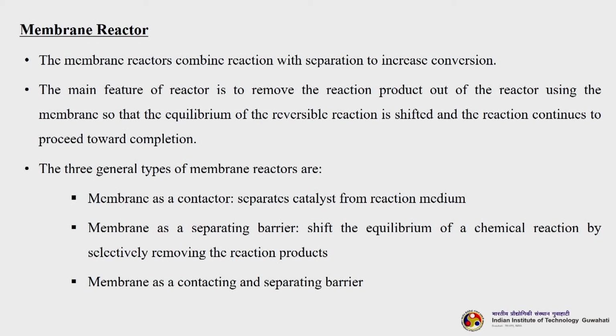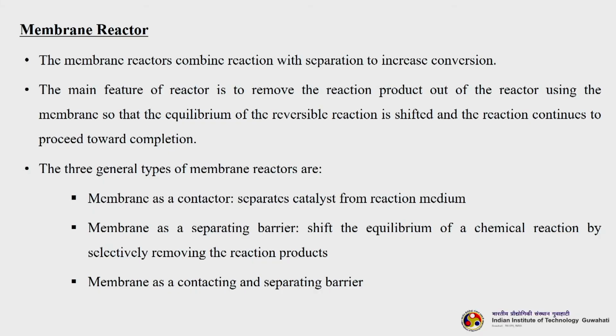The main feature of the reactor is to remove the reaction product out of the reactor using the membrane, so that the equilibrium of the reversible reaction is shifted and the reaction continues to proceed toward completion. So, I am continuously removing one of the reaction products which is not a value added product for me, so that the main product yield will be higher than that of the byproduct.